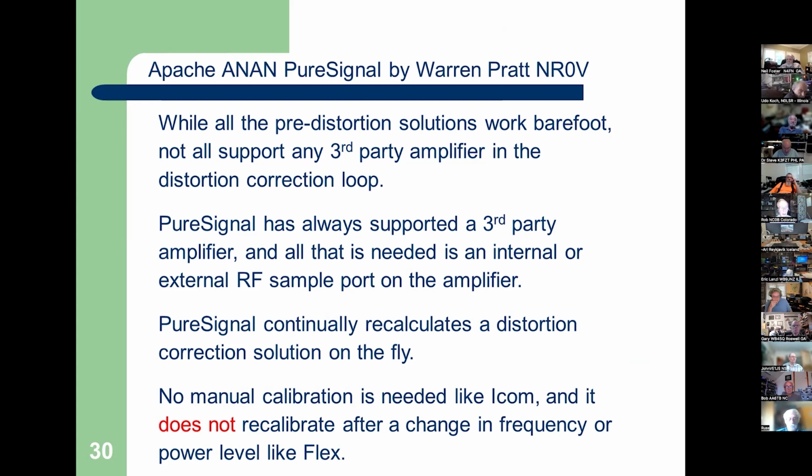Now the ICOM is different. You have to calibrate the ICOM into a dummy load, and it doesn't recalibrate one way or the other. It's just what it is. With the Flex, it will recalculate a solution if you change frequency by more than 10 kilohertz, or if you adjust the power level by even 1 watt, which seems a little silly.